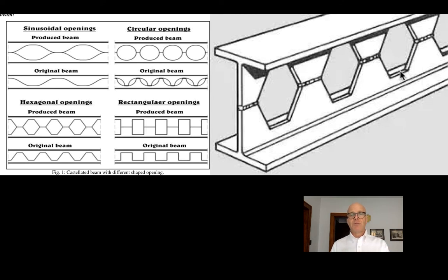The section modulus of a beam, the measure of its efficacy in bending, is inches cubed. Inches squared is area, and the third factor is one of just pure length. So remember, in section modulus, we're measuring not just the overall area, but we're multiplying each one of those little areas times its moment arm around the neutral axis. So if you look at what we've done with the castellated beam, we've taken a W shape that is, say, maybe 6 inches deep, and now we've made it maybe 8 inches deep. We've taken the webs and literally just given them that extra moment arm, and it's cost us nothing in terms of material.